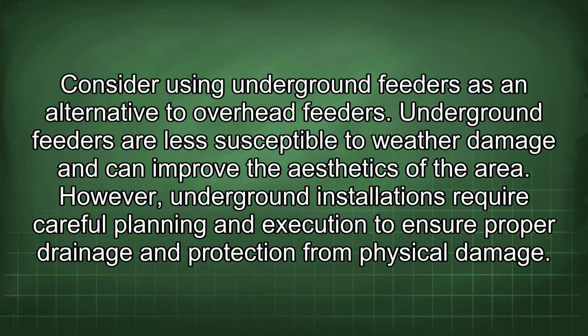Consider using underground feeders as an alternative to overhead feeders. Underground feeders are less susceptible to weather damage and can improve the aesthetics of the area. However, underground installations require careful planning and execution to ensure proper drainage and protection from physical damage.